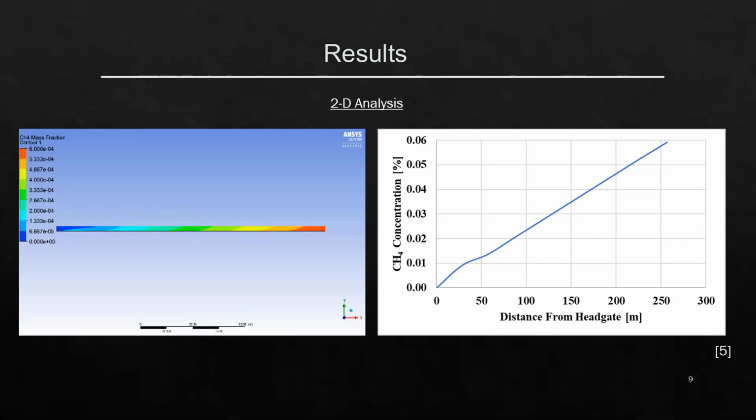Like I said, I have the energy equation turned on. It's a transient model, and I implemented the k-epsilon model as the turbulence model, and then I have a species transport running with only methane and air defined as the two species interacting. And there's no ignition. It's not an ignition, it's just a mixing thing. So I don't have any source of ignition or anything like that.